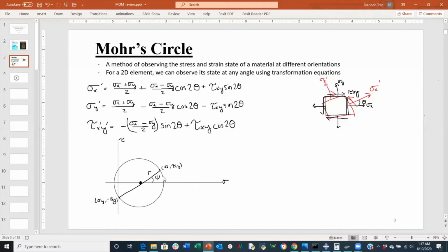Okay, so the development of the equations for Mohr's circle. We have an average stress here, which I'm going to denote as stress average, and a radius. If you guys remember the equation of a circle, it's something like a squared plus b squared equals the radius squared. We basically take that same notion to develop the equations for Mohr's circle, where we try to essentially state the stress states at this point right here and this point right here, which we would denote as sigma 1 and sigma 2.